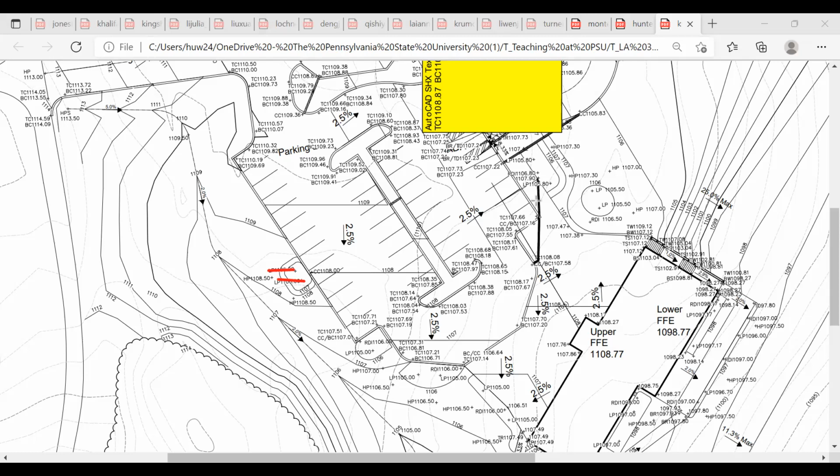Okay, so this works. I'm not saying this doesn't work. It's just some more excavation than necessary, because you're essentially lowering your cell by a foot, right? So the depth here is correct, but your RDI can be a little higher. 1107, that's 06. Yeah, you wouldn't have water going inside of your cell there. That's cool. And for the one at the bottom, BC equals 106.64. Yeah, works. There's some conflict of 07 conflicting with 06.